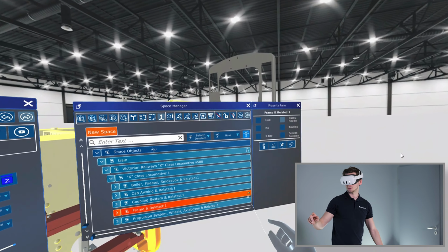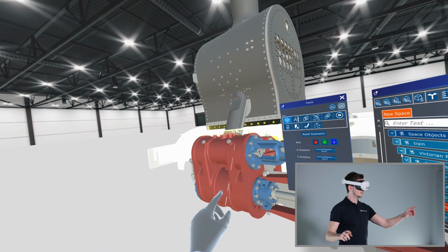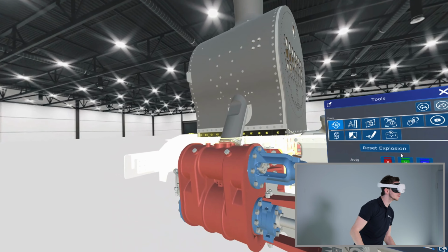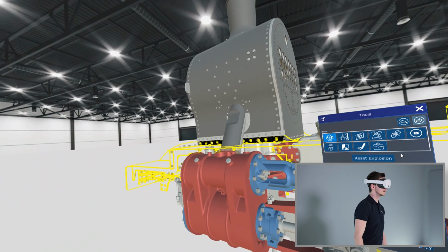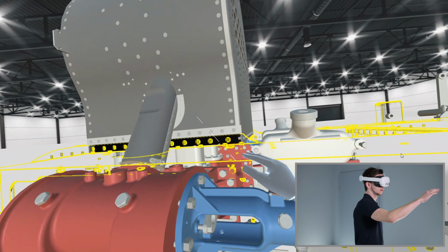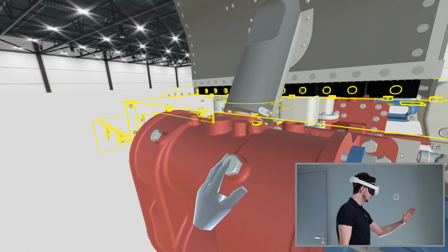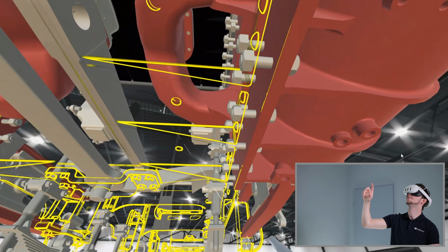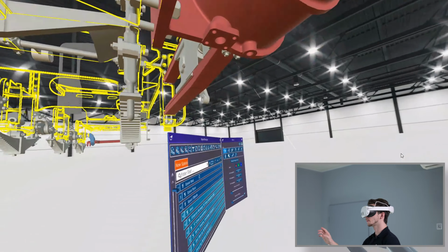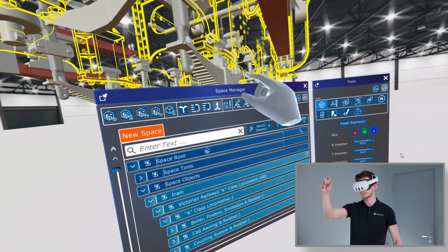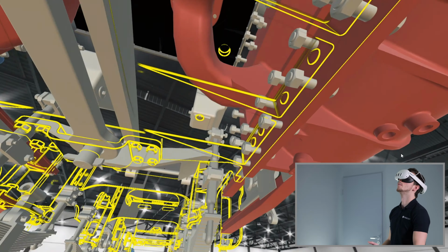An additional way to focus on the details of the model is to enable the X-ray visualization mode. X-ray gives you the possibility to apply some transparency and, for example, enable the outline system. The outline system detects the edges of the geometry and focuses on the lines, for example, to be able to overlay a specific design with physical parts to detect defects or design flaws. One of the typical use cases for the outline is, for example, to detect if the holes for bolts are matching between the design and the physical product. In this way, you can just compare the design and see if the position is correct to the millimeter.